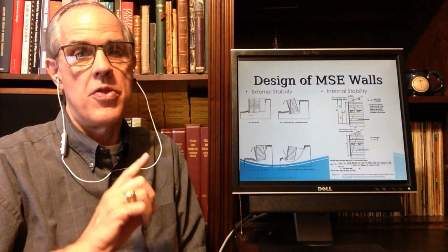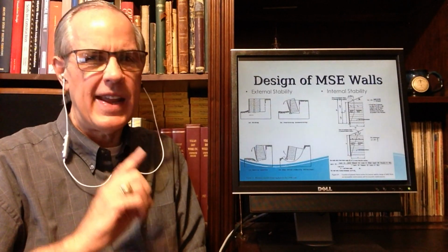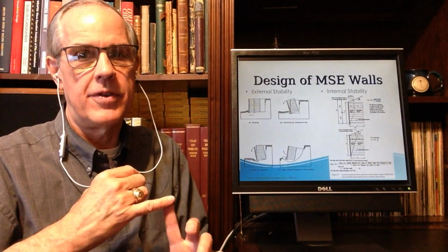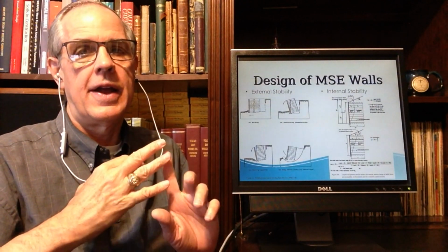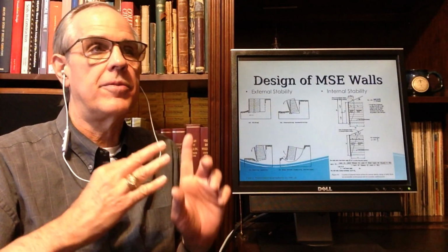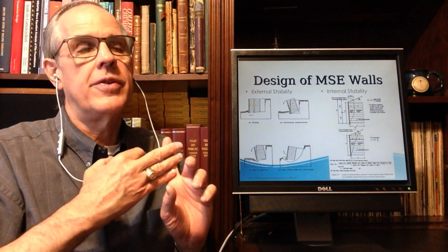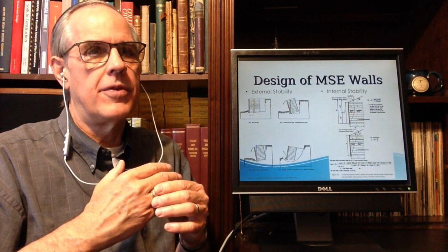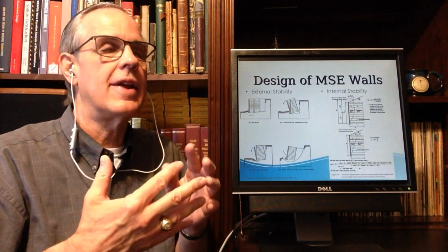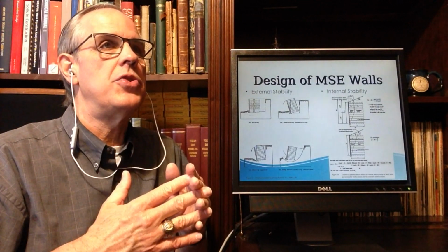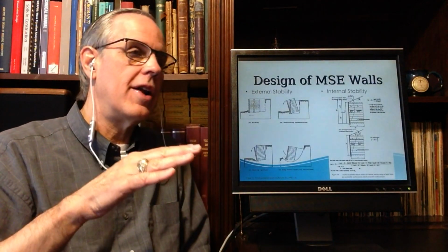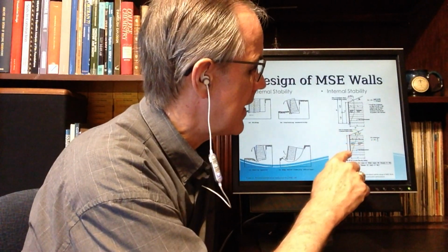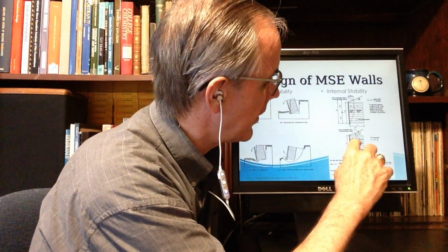Therefore, what we need to do with any wall reinforcement, it doesn't matter if we're talking about the strips here, any anchorage systems, soil nailing, if we do it that way. Of course, soil nailing is a little different, which we'll talk about. But any kind of rock anchorage or anything like that, we have to put the anchor long enough and far enough into the earth to get past any kind of failure surface, in other words, over here.